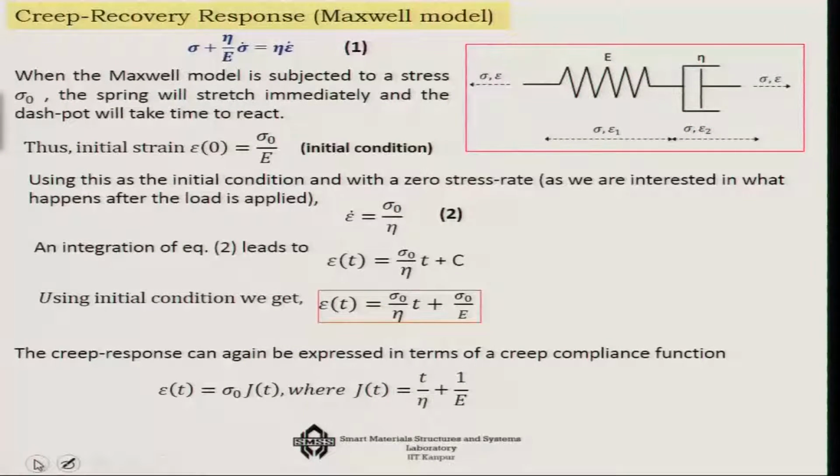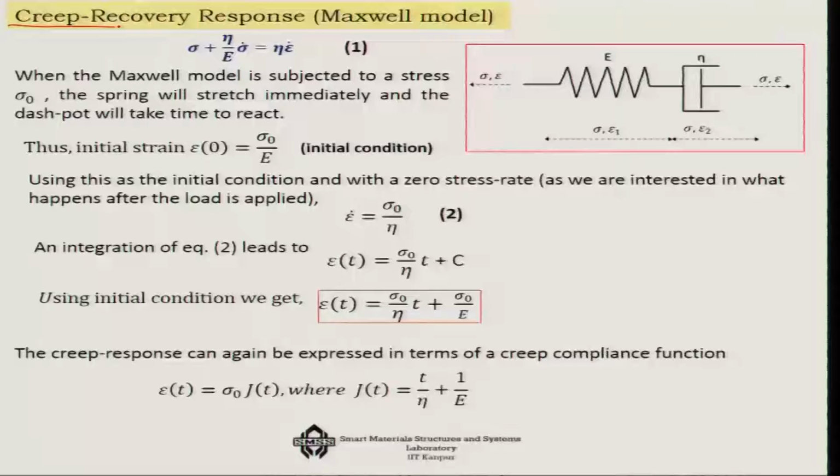Next, let us look at how this proposed model is going to behave with respect to two things. One is the creep recovery and another is the stress relaxation. Now, when we talk about creep recovery, you have to keep in mind that we are going to apply the force only once and then we will keep it steady. That means it will behave like a Heaviside function.